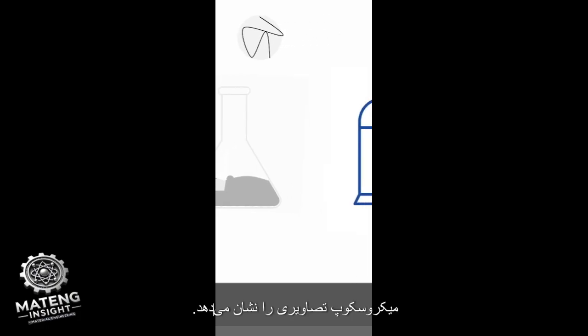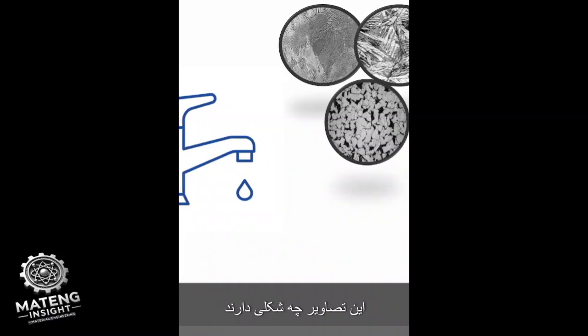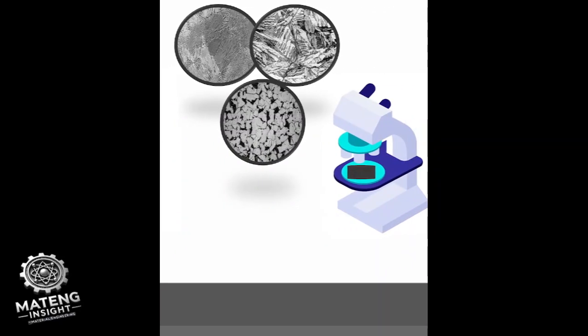One of the most common compounds of etching solution is nital. During the etching process, the color changes in areas with high energies, such as grain boundaries. So it helps to distinguish the grains, their boundaries, or their orientation. The microscope reveals some pictures. What are these pictures like, and what do they mean?